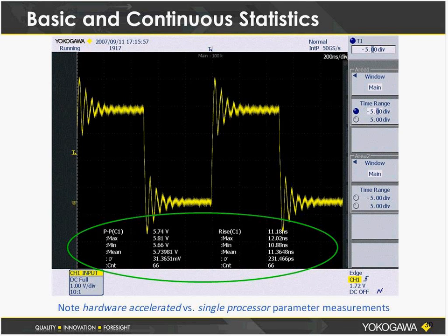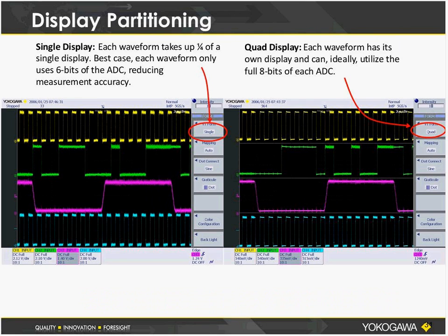This is another factor that can influence the accuracy of your measurement, and it's display partitioning. So an oscilloscope, again, is going to have a limited display in which you have to potentially look at more than one signal. And if you find yourself resizing the signal manually or repositioning them vertically on the display, it is also potentially dangerous to your measurement simply because you are actually reducing the gain if you reduce the voltage per division in order to take less of the screen.